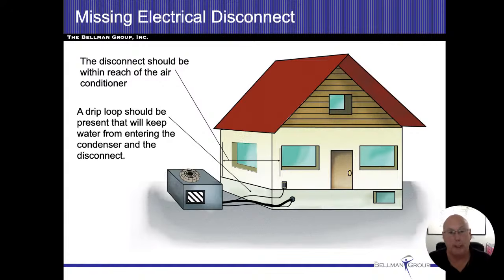It's a good idea to check those connections at both ends. If they're metal, liquid tight, flexible conduit, then we can use the conduit as our grounding system. If the connections are plastic, then we're going to need a separate ground wire that comes through it, so that we can make sure the breaker will trip should we get a ground fault in the cabinet anywhere. So I like to check those connections and make sure that they're nice and tight and secure. And if they're loose, we've got a paragraph for that too that we'll put in the report.